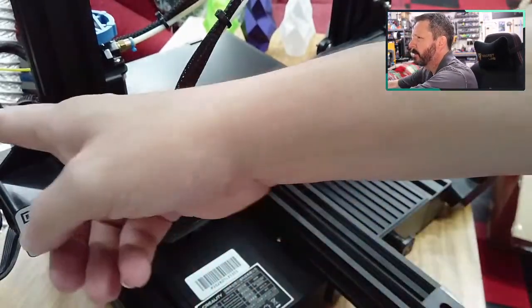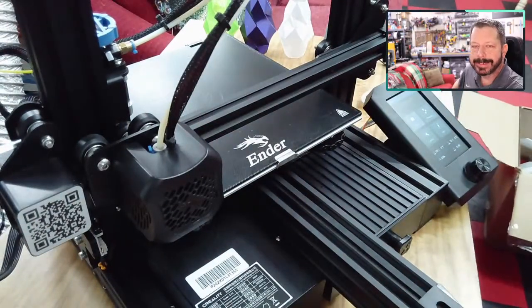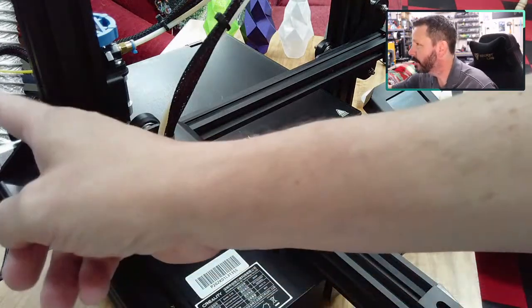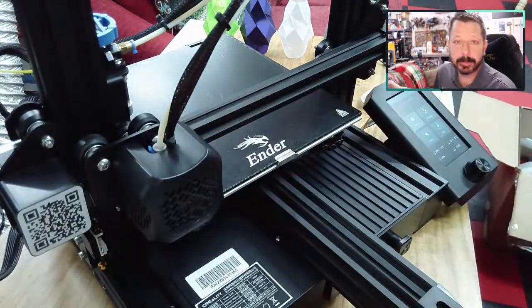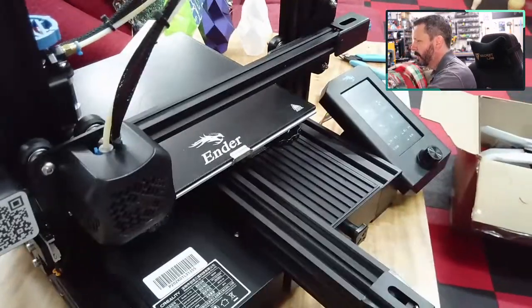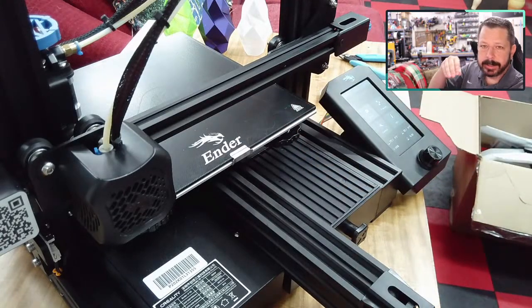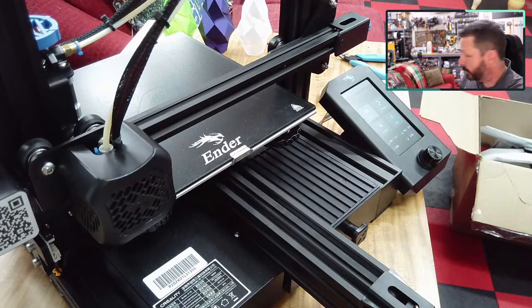One thing, sometimes your filament has broken. If you leave your filament in your printer for an extended amount of time, it can get brittle and just snap over here somewhere, and you don't have any filament feeding. That doesn't seem to be the case. I do have filament in. Sometimes your nozzle is just too close to the bed. So it's like the nozzle is smashed down onto the bed where there's no room for filament to come out. That's probably what's going on here.